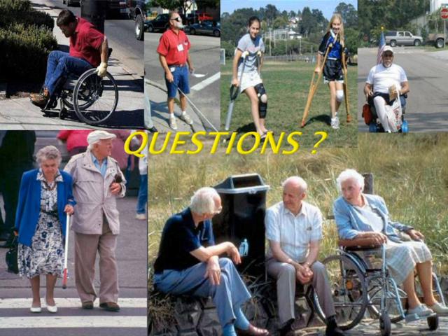Okay, I think it's always best to keep drainage away from the ramps. I talked to one person who's actually wheelchair-bound. He's the president of the Paralyzed Veterans of Michigan. And he said that if he sees standing water at the bottom of the ramp, he won't even use it because he can't see what's under it. He doesn't know if there are any potholes or dips under it. So try to keep drainage away from the ramps.